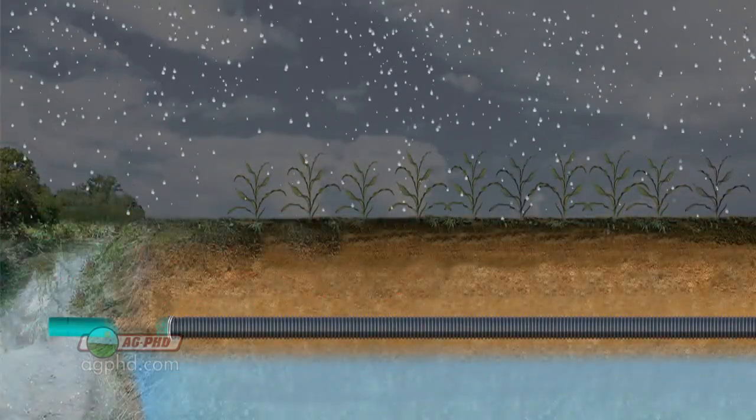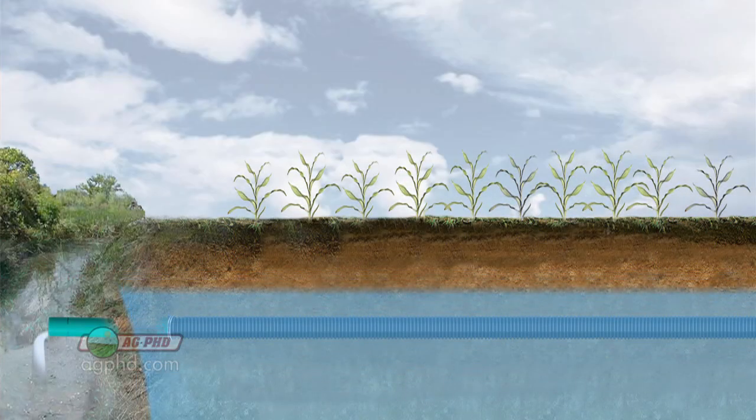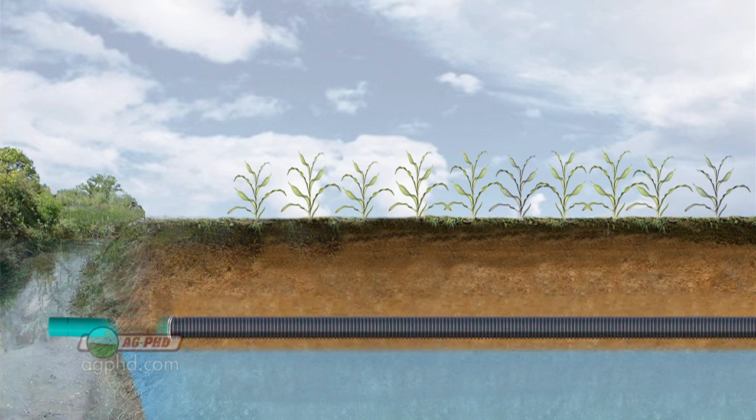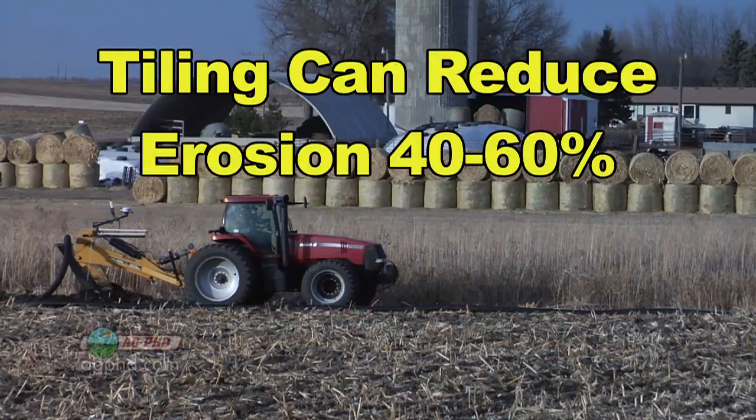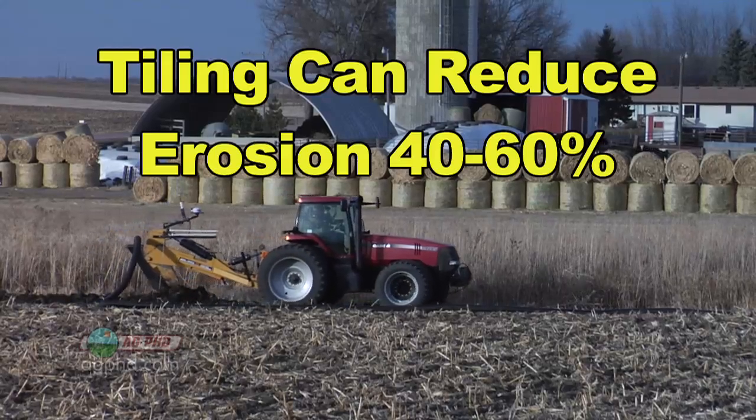When you get rain, no more water can get absorbed by the soil, so what does the rain do? Well, it has to run off. When you have tile out there, you lower the water table. Now you have capacity to hold moisture, so now when you get a rain, the rain soaks in. And most studies have shown by tiling you can reduce erosion 40 to 60%. That's a big deal, and it's a conservation practice we're doing on our farm.